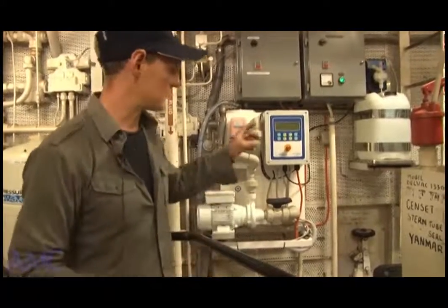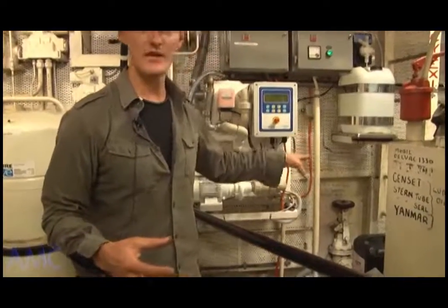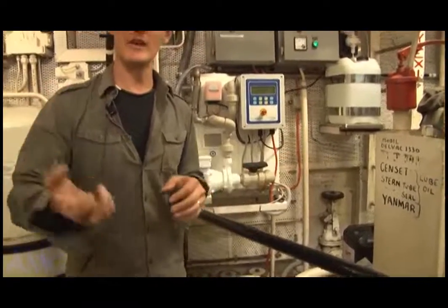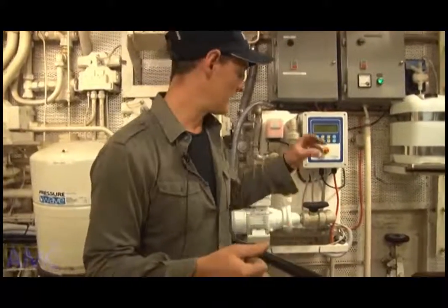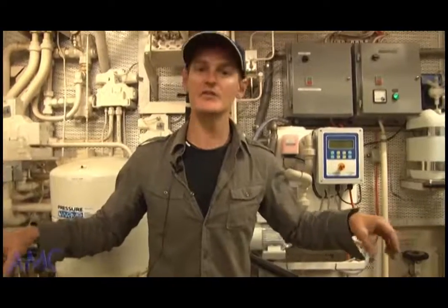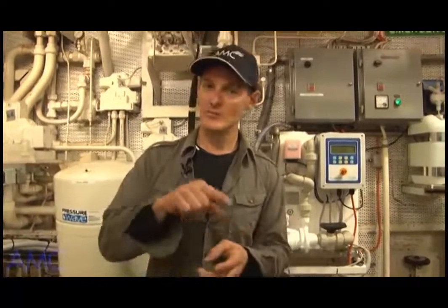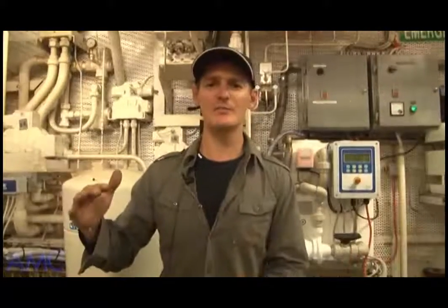This one valve is our filling point, and it's also our discharge point, or our suction point really, for our transfer pump. So it's a remote quick closing valve, and we'll activate this in a moment. We'll have a look at how we can close that remotely from on deck, and how we set that up and reset that valve. And we've also got a day tank as well. So from our bunker tanks we use a purifier, and we purify to our day tank. The day tank is basically a smaller tank which gives us one day's worth of running.